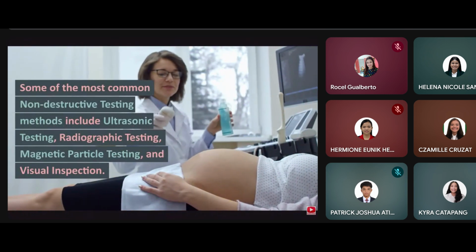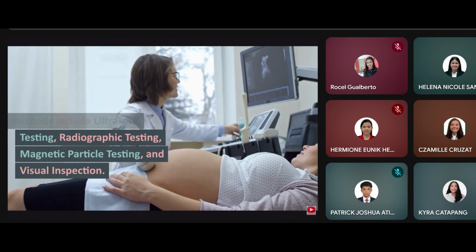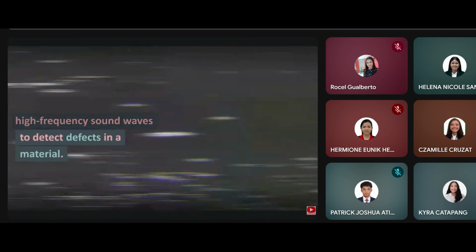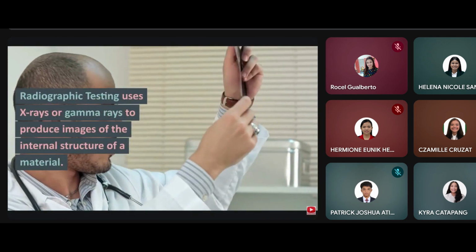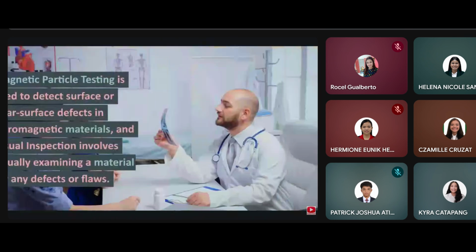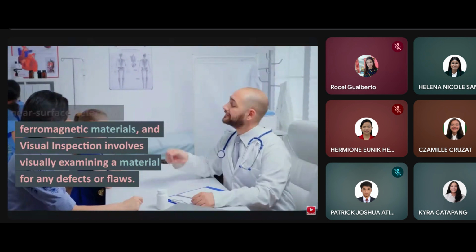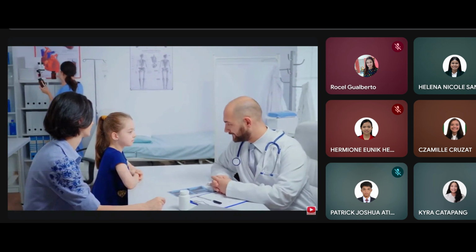Some of the most common non-destructive testing methods include ultrasonic testing, radiographic testing, magnetic particle testing, and visual inspection. Ultrasonic testing uses high-frequency sound waves to detect defects in a material. Radiographic testing uses X-rays or gamma rays to produce images of the internal structure of a material. Magnetic particle testing is used to detect surface or near-surface defects in ferromagnetic materials, and visual inspection involves visually examining a material for any defects or flaws.